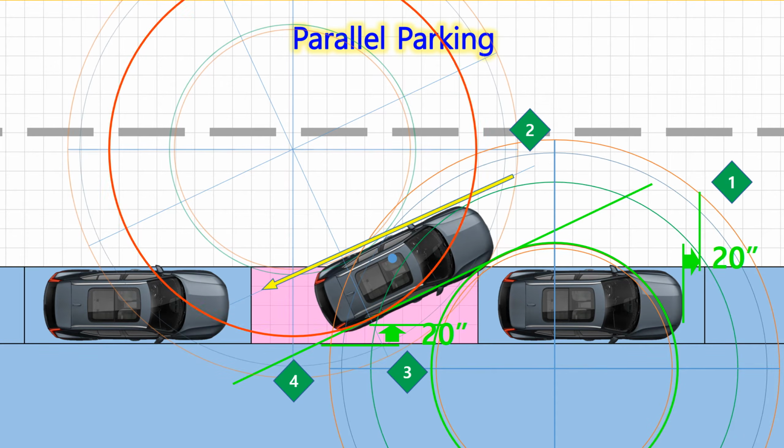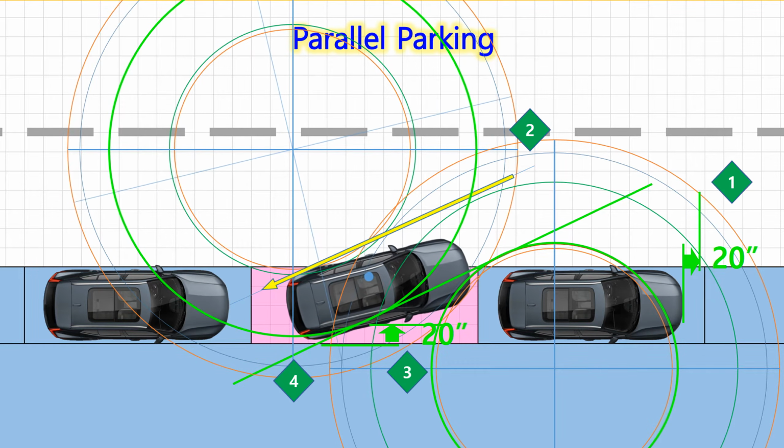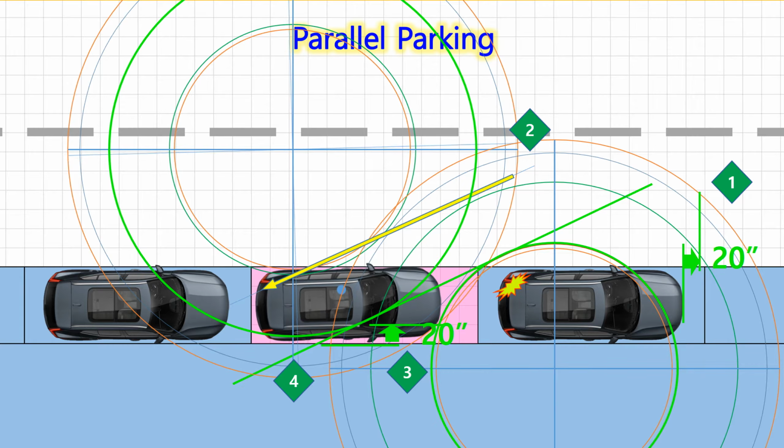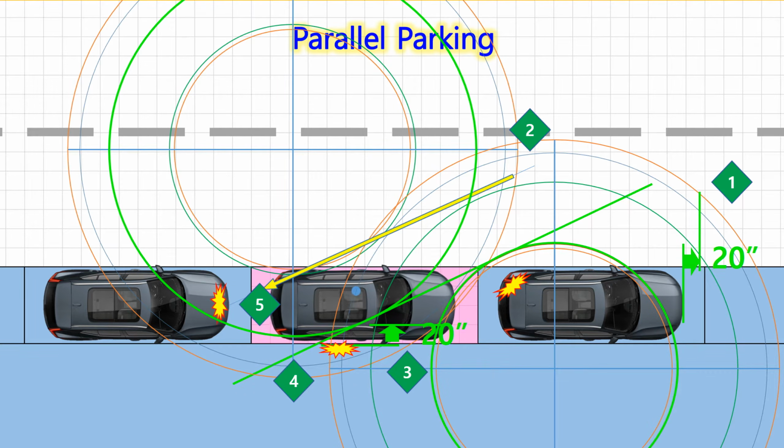4. Turn the steering wheel to the left all the way, and turn your vehicle till your car is parallel to the curb. Make sure that your car doesn't hit other cars. 5. Complete parking in the middle of the parking space.